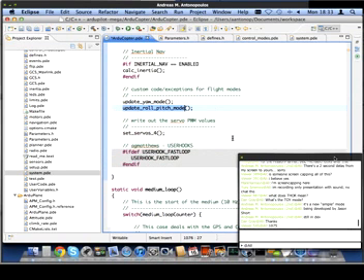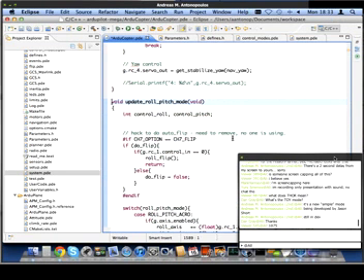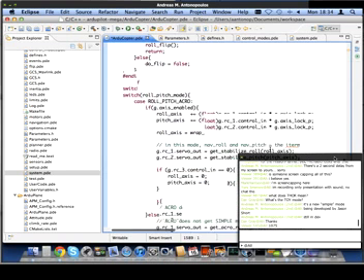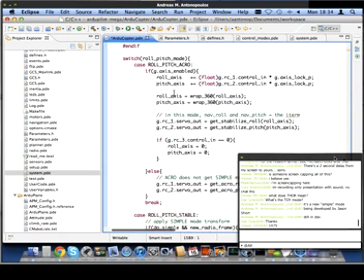This is where we actually make use of the yaw mode and the roll pitch mode. These functions here are being called at 100 hertz, like I mentioned. The throttle mode is actually called at about 50 hertz, a little bit further down, but never mind that. Right, if we can now go to update roll pitch mode, which is in ArduCopter.pde at 1589. Sorry to jump around.